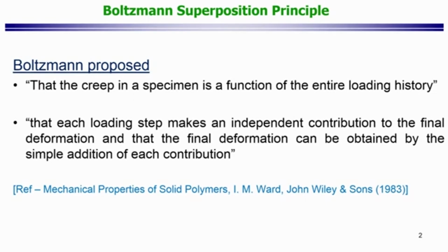And here what this book says is that Boltzmann's proposition was that the creep in a specimen is a function of the entire loading history. That is number one. So, you can see that Boltzmann is bringing in the idea of memory right here, that you have memory built into the system. It is very elegantly put. And then each loading step makes an independent contribution to the final deformation, and the final deformation can be obtained by the simple addition of each contribution.